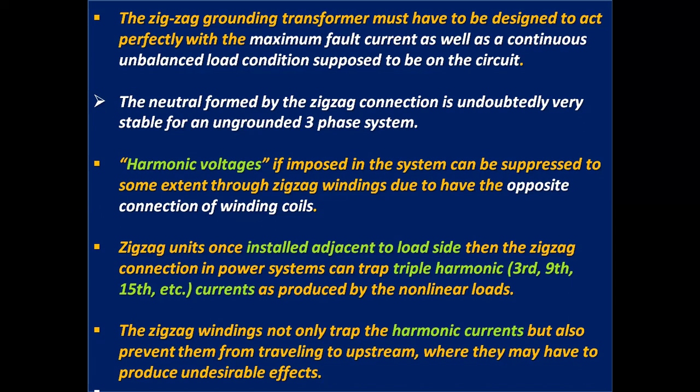Most important, the zigzag windings not only trap the harmonic currents, but also prevent them from traveling upstream, where they may produce undesirable effects.